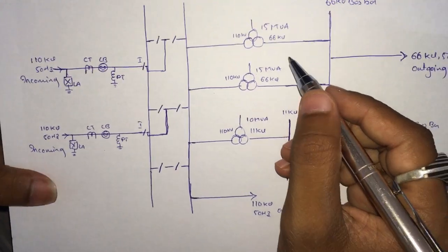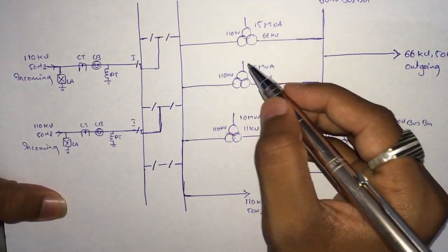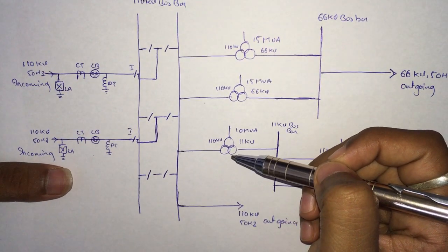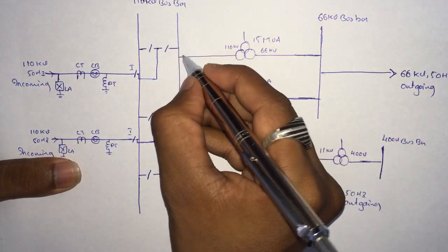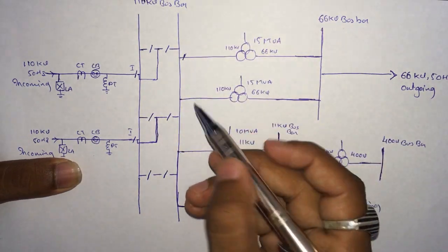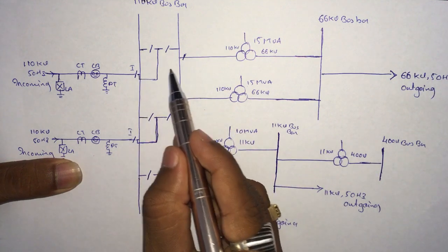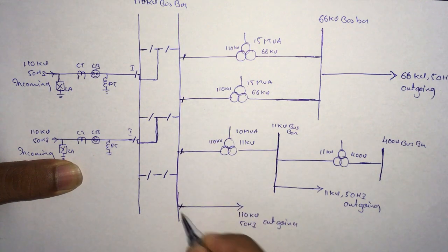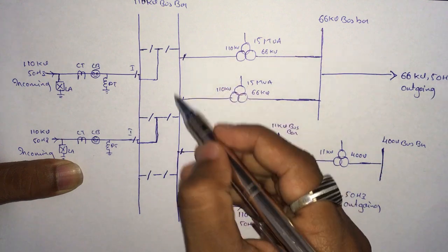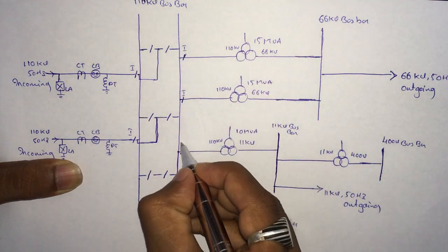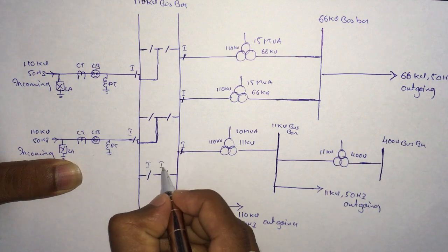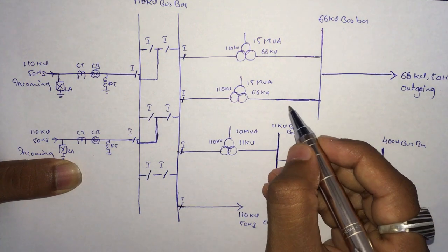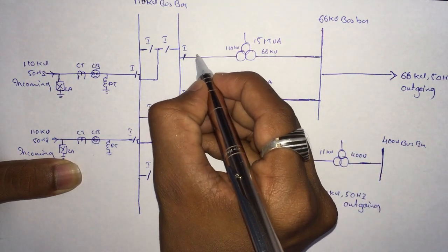Okay, after that we'll come to the heart of the substation or generating station, that is a transformer, which is the costliest equipment in a station. Okay, after the bus bar we'll be using an isolator. Remember, entering the bus bar and leaving the bus bar we'll be having isolators for all the lines. Okay, we'll be using isolators I. Mark it as I. After that circuit breaker.